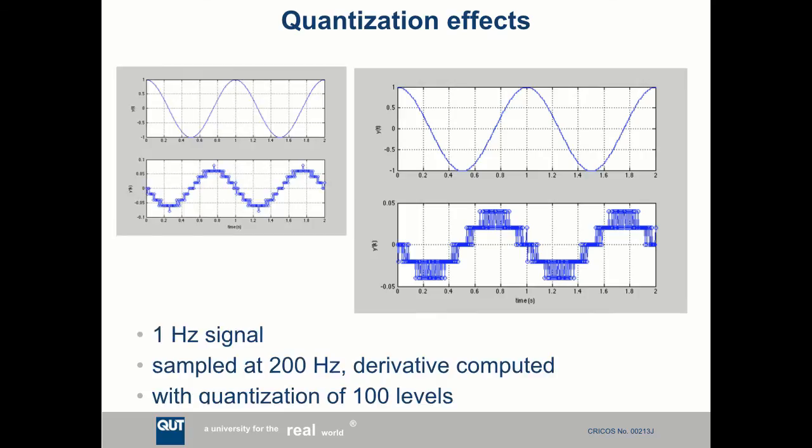So this is a case where reducing the sample time makes implementing something like this very difficult. So here's another example where I have doubled the sampling rate again, and we can see the signal is incredibly quantized now. There's really only 1, 2, 3, 4, 5 possible values for the velocity. And if I double the sampling interval again, there'd be probably only 2 possible values of velocity coming out. And the signal is now really noisy, right? It's this horrible ragged step thing with all this kind of grass on it.